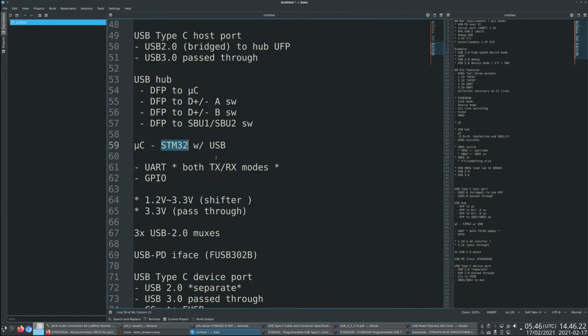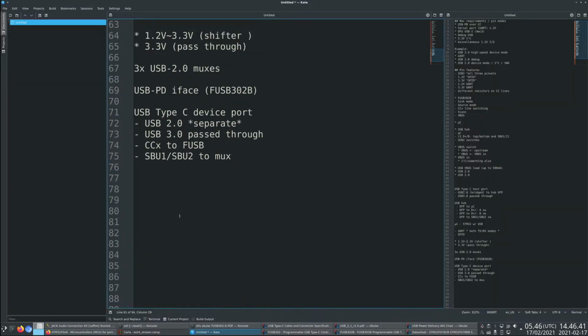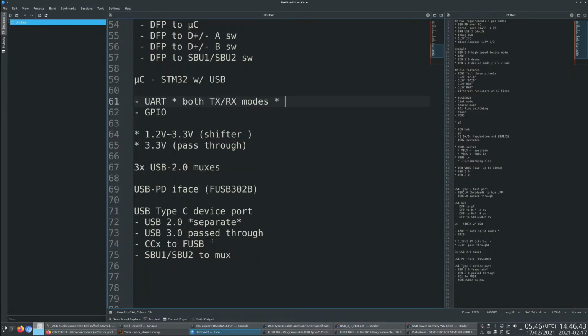So my idea is, why don't I just bridge those pins? I take the 2 sets of pins that can do USART1 TX and RX, and I connect them crossed over, so that depending on which set of pins I pick, I can just switch over TX and RX. And then we have 3 USARTs, so those 3 can be for all of these 3 different pin sets.